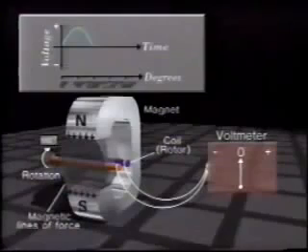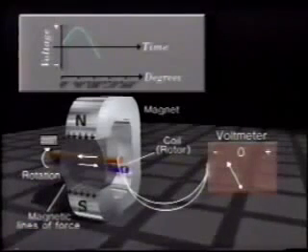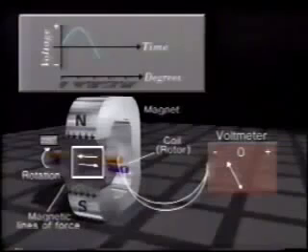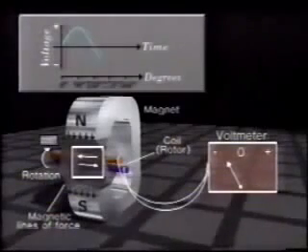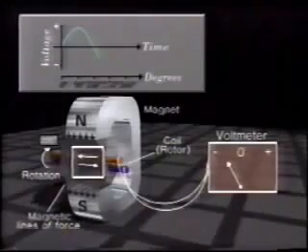As the coil continues rotation past this 180-degree position, the conductors are cutting flux from a different pole. The red conductor is now in front of the North Pole, and the blue conductor is in front of the South Pole. So the voltage generated is now in the opposite, that is, negative direction.